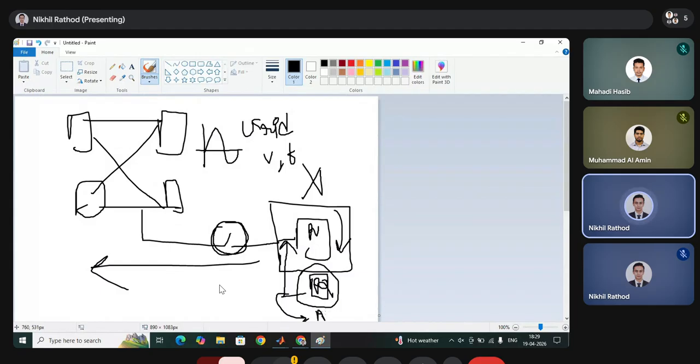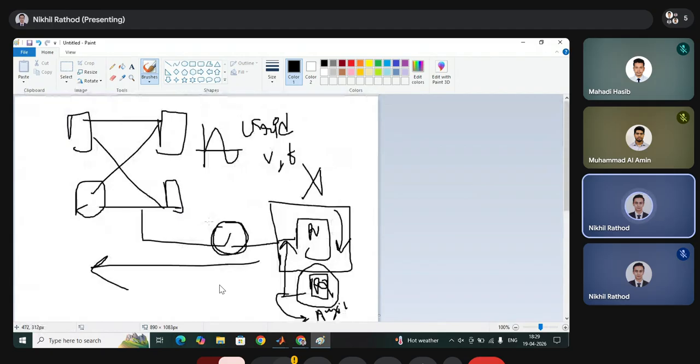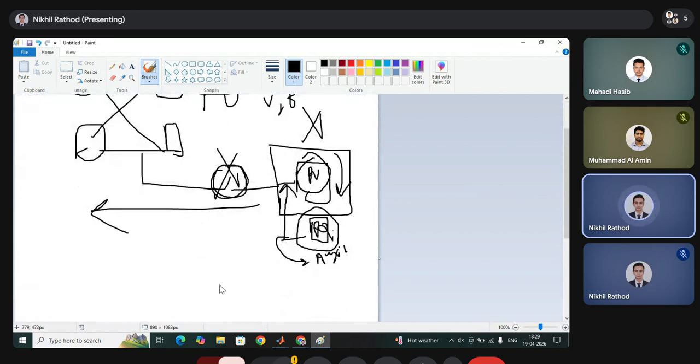by the auxiliary system. Auxiliary means, if you are working in a thermal power plant, you run the boiler, pumps and electrical motors, which are auxiliary loads, and those are fed by this PQ generator. If some abnormality happens and you are disconnected from the grid, this breaker is tripped, isolation. In that condition, the PV generators are isolated, but the PQ generator remains in the picture and controls and supplies power to the entire power plant, the entire necessary load. So this is the importance of the PQ generator. You can consider it a backup generator or DG generator also.